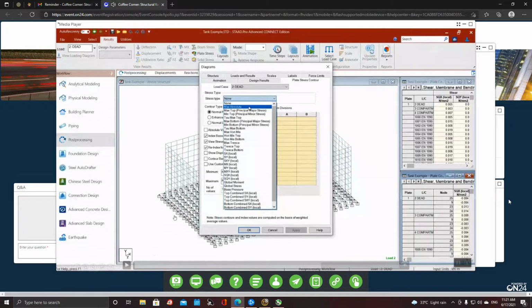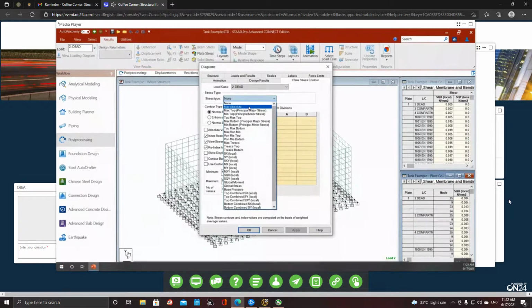Because it is a sort of non-linear problem: the springs are active only for compression forces and inactive for tension forces. Hence, the stiffness matrix will change according to the load. That's why you need to combine the loads using realistic combinations like repeat load and reference load, and not use the load combination feature.